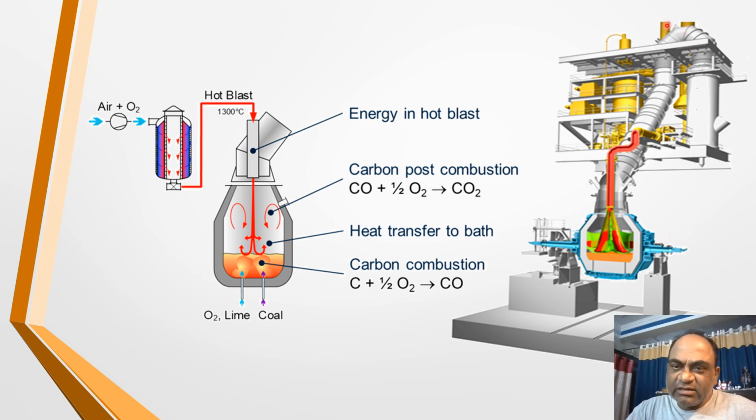This is the entire mechanism of gas recovery, or of putting the raw material into this vessel as part of the addition of materials. Sometimes coke is also added, limestone is added. All these bins are kept here, and with the command from the screen in the control room, only then can these materials be added into the vessel.